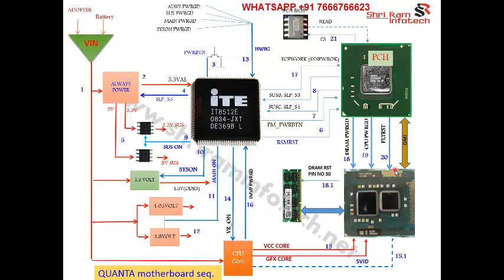The platform reset is 3 volt, and this 3 volt resets the entire motherboard. But when it reaches the CPU, they use a resistor to drop that voltage, because the CPU's maximum voltage is 1 volt. So how can you give 3 volt to reset? So they use a resistor over there to drop the value. That voltage is called the CPU reset.